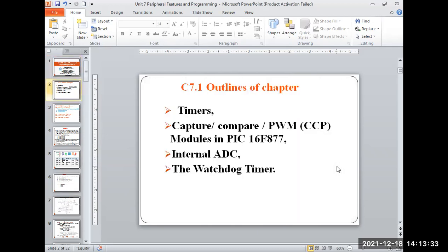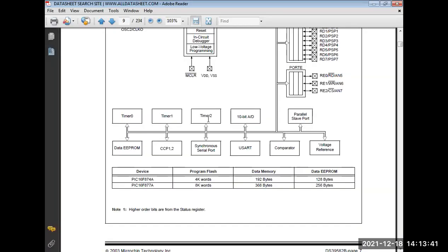Okay. So in that, what we have seen is just timers. If you look at the diagram, it has timer 0, timer 1, timer 2. So how this timer internally operates and how it supports 8 bit means the maximum count can be 2 raised to 8, which is 255, that is 0 to FF in hexadecimal. So when the timer internal registers TH0 and TL0 reach the maximum count, rollover occurs and the interrupt will be generated. That we have to see in chapter number 7 specifically.